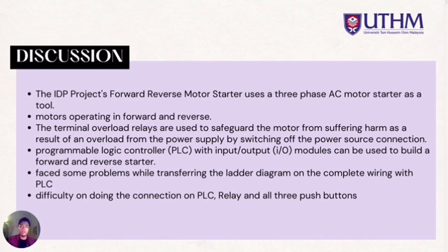There are two challenges that we faced while doing the construction system with the PLC in the IDP project. We faced some problems while transferring the ladder diagram on the complete wiring with PLC. At first, when we transferred the PLC program, the PLC could not synchronize. Then we did the troubleshooting and found the model of PLC we used was not the same as we set, which is we use CP1E E20 in our project.